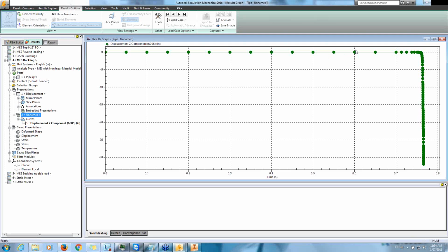Otherwise, the time step size is 0.1 seconds, as you can see here. But once things start happening, which is what you want to capture right here, it wouldn't be able to capture that for you. The critical portion of the analysis won't be captured unless you check. It will be calculated but not saved, but you want it to be saved and displayed so you can determine when buckling happened.